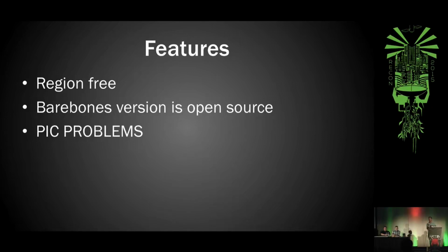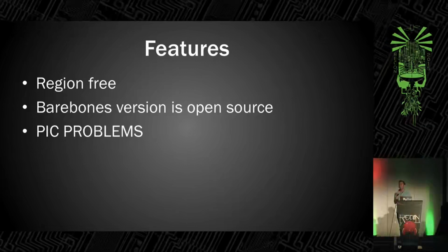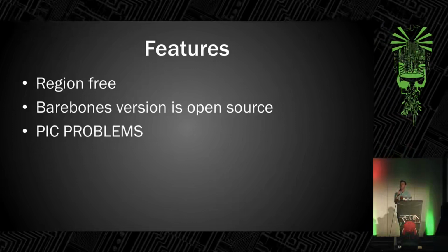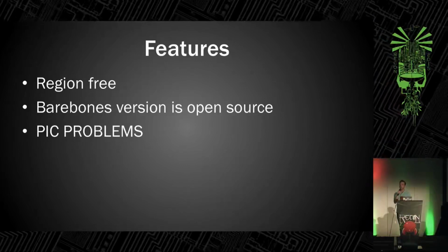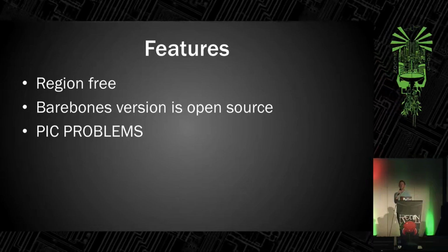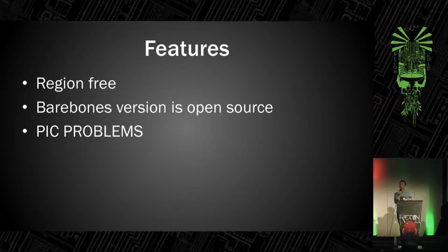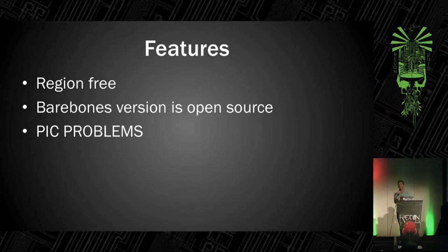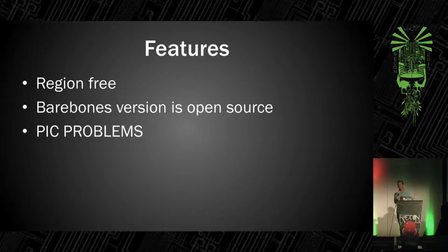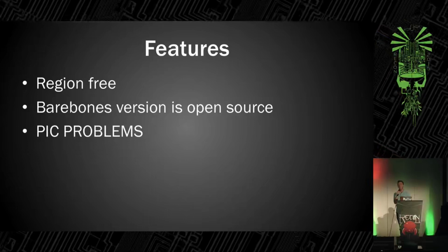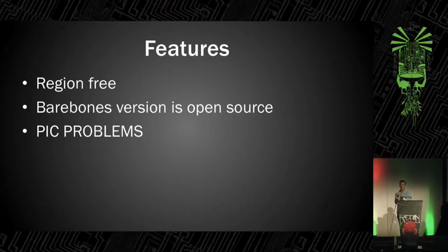So we wired up a PIC to the same clock, and we thought, great, we're going to have twice as many instructions to actually implement the same thing, because we'll be running at the full external clock speed. Well, fun fact about 8-bit PICs, they actually run at 1/4 the external clock speed. So we had half as many instructions. That didn't work out. Luckily, Microchip makes a pin-compatible part to the one we originally spec'd, and it has an internal 4x PLL. So we were able to get around that. So I guess you win some, you lose some with PIC.